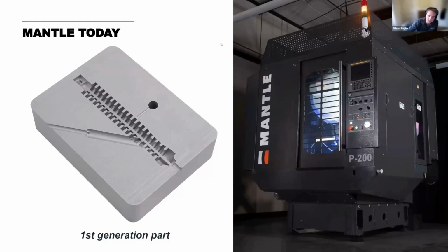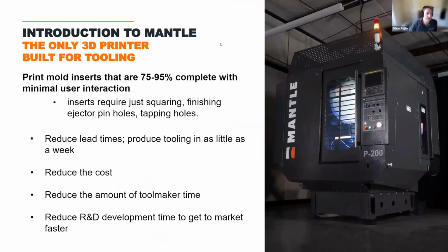If you're not familiar with Mantle, we say we are the only 3D printer built explicitly for tooling. It was designed specifically for that application. It's the only application we target, and today, that's mostly injection mold tooling. Our technology prints mold inserts that are 75 to 95% complete, depending on the application, with very little to minimal user interaction. Generally, inserts require some squaring, finishing of ejector holes, and tapping of any holes. So very minor finishing after the printing is complete.